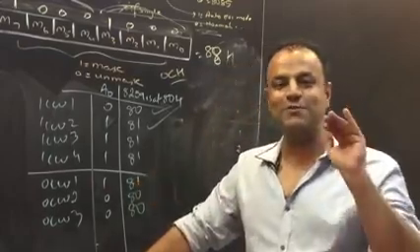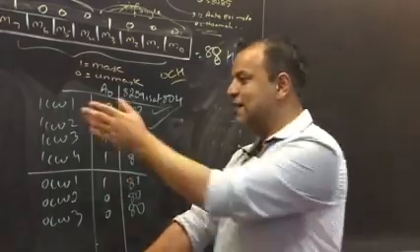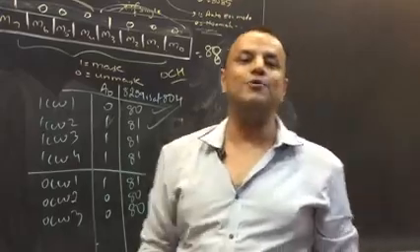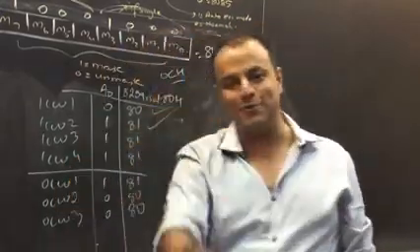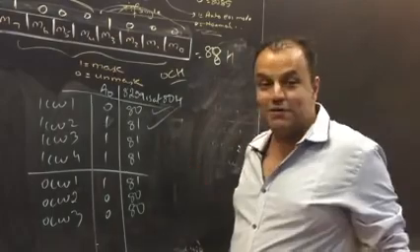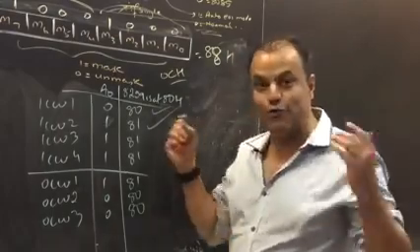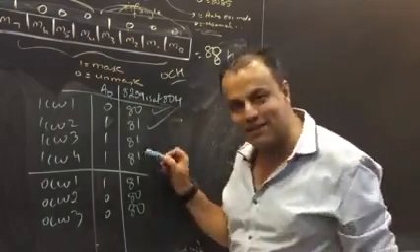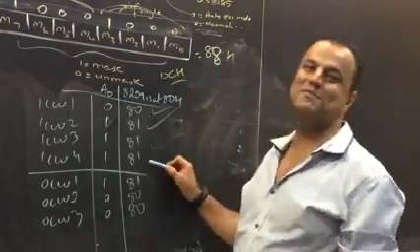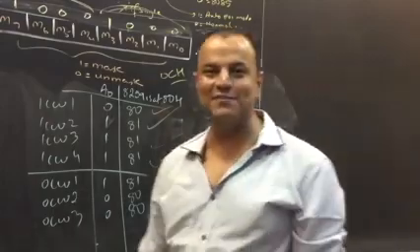Suppose I have told you I am giving you ICW4 and not ICW3. That means ICW3 is out of the picture. At 81, the next command is ICW4. Are you understanding what I am saying? Because I have told you in ICW1 whether I am going to give you ICW3 and 4. Even if I am giving you both, and I've told you I'm going to give you both, that means they will come in this order only. That means the first command at 81 will be ICW3, the next command at 81 will be ICW4. Tell me, will you be able to identify these 2 commands?